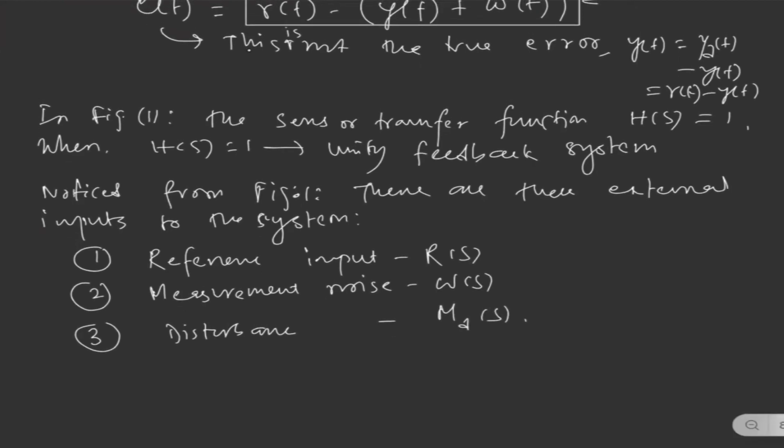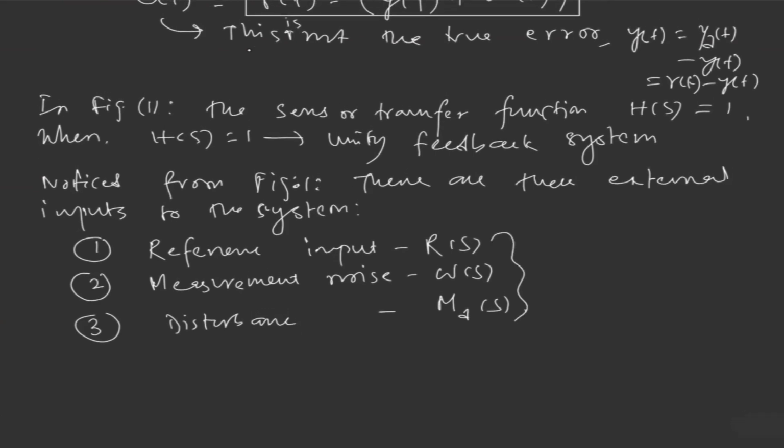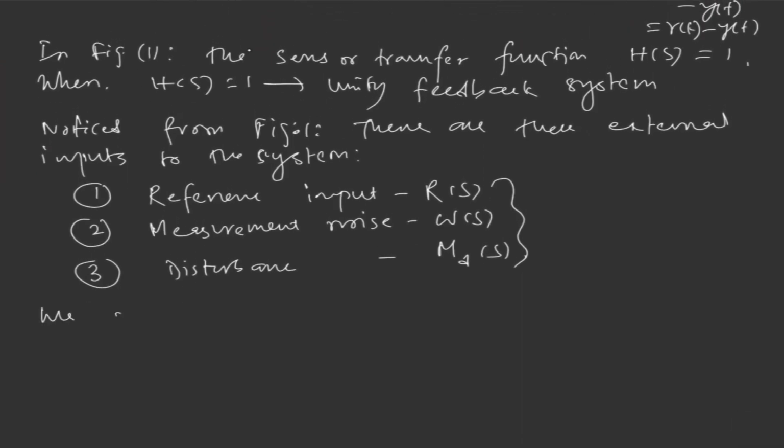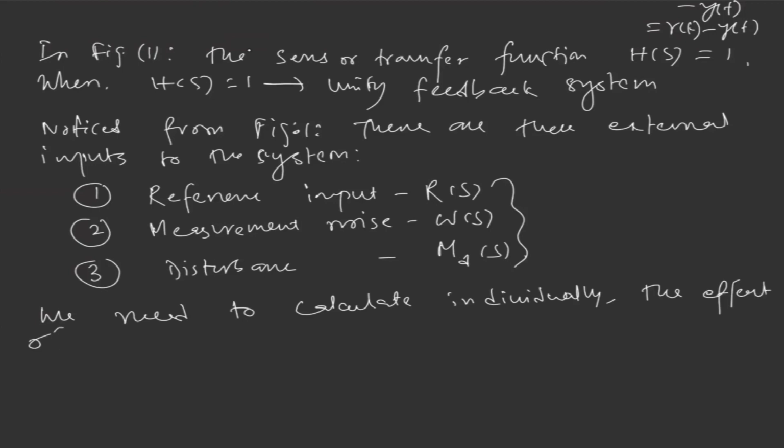But as per the transfer function concept, this basically relates a single input and a single output. But we are having three inputs. So we need to calculate individually the effect of the inputs on the output.